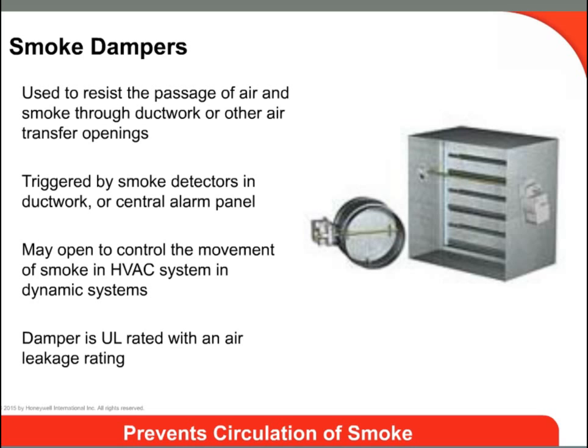Smoke dampers in the U.S. must meet the UL 555S rating. Like the UL 555 rating, dynamic dampers will also have an airflow velocity and pressure differential rating. UL 555S smoke dampers also have leakage ratings. The actuator must also be able to operate the damper at elevated temperatures and be tested to 20,000 actuator cycles. Smoke dampers are rated to 250 or 350 degrees Fahrenheit.